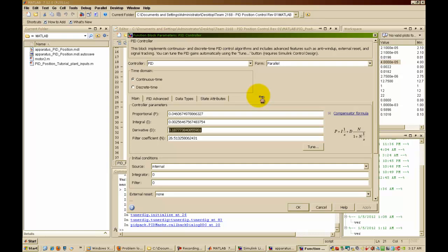Make sure the final gains that you run are tuned when you're running the robot in its natural environment. It's okay to try and tune the gains for the first time with a robot on bricks in order to get a ballpark response. You got to run it under load, because what might work when it's suspended will probably be too small and underperform when it's under load. You got a 120-pound robot that's on those wheels. It's definitely going to be a noticeable difference.